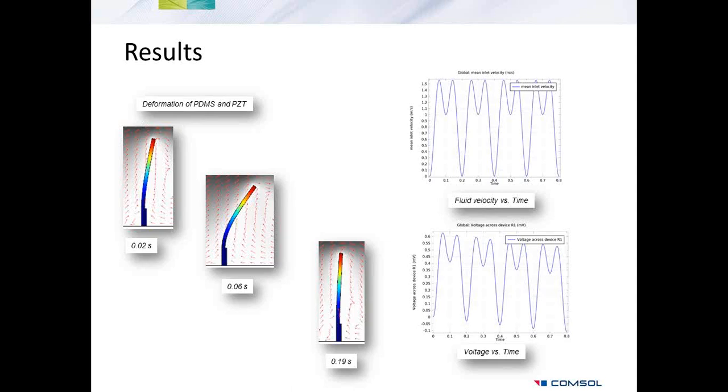The drift can be tuned by altering the time constant of the sensing circuit, which in this case would involve changing the resistance connected to the piezo material. So we see that multiphysics simulations not only help us in quantifying expected behavior, but sometimes it also helps us to unravel and understand the underlying physics involved in the device design process.